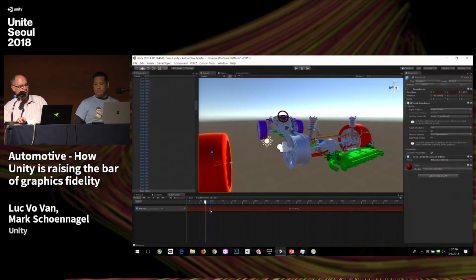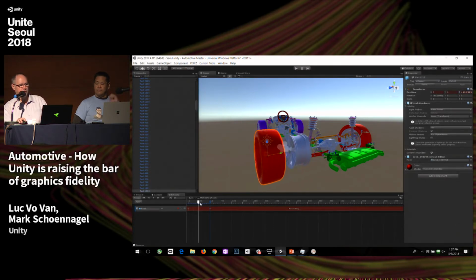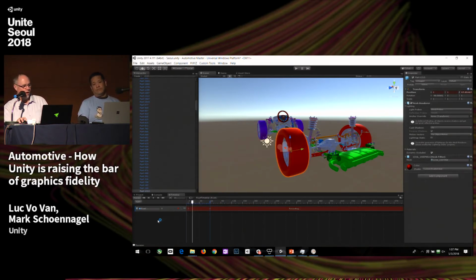So I go to where I want the object to live. That sets a keyframe. I'm going to go back to frame 0, and rather than slide this back, I'll just go here and press 0. So that resets it back to the beginning, or to its original position, and just that easily I've created a simple animation. I could do a bunch more, but let's just do one more here.